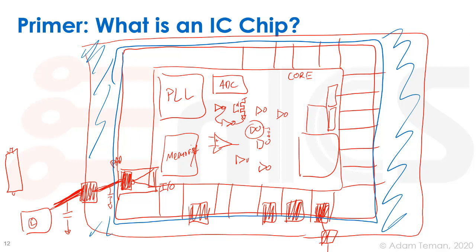So I just want to say one more thing. We have this battery now, and the battery is connected to the chip in some way, again through these pads. We're going to drive these voltages into the chip. How do we bring this voltage over so we have a VDD and a ground on this guy? What we're usually going to have is all kinds of wires inside the chip that are going to move this VDD and ground over to the gates.